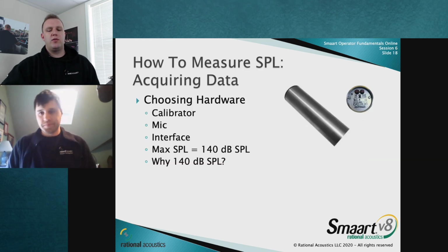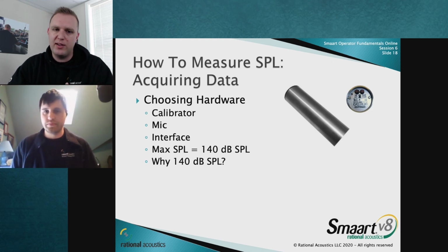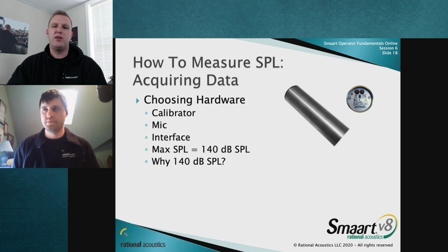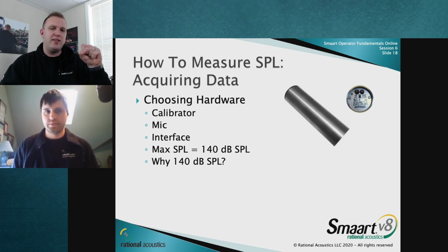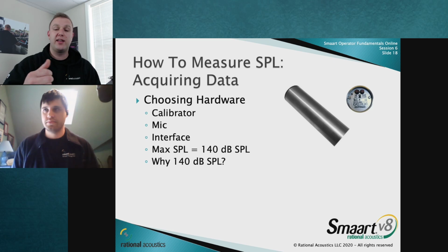So how do we actually get SPL data, right? What are the pieces and components that go into acquiring SPL? First of all, we need to calibrate our SPL reporting device so that we know that it's accurate. And this is typically done with what we call an SPL calibrator. They used to be known as SPL piston calibrators, where there would actually be an airtight seal with a piston pushing a specific pressure value against the capsule. We do this electronically now.